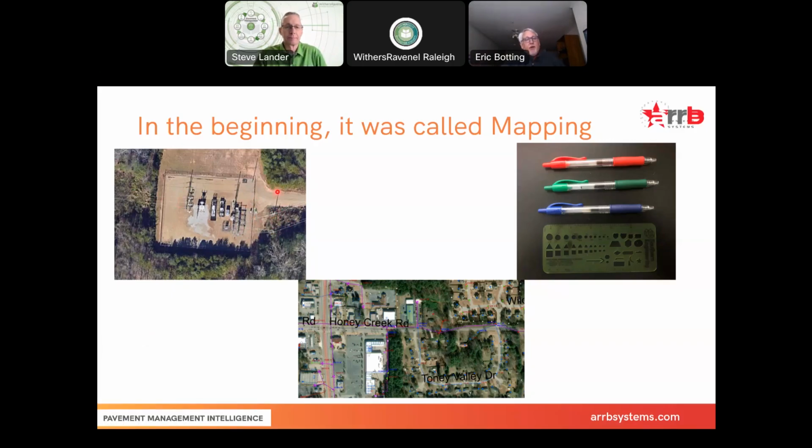But the point is, I would have something like this, and I would go literally pole by pole. I'd locate the pole. I'd do the inventory, do all of the basic connections. If there's a transformer, it's going to drop to a meter somewhere, get the meter number, everything would be on the map.